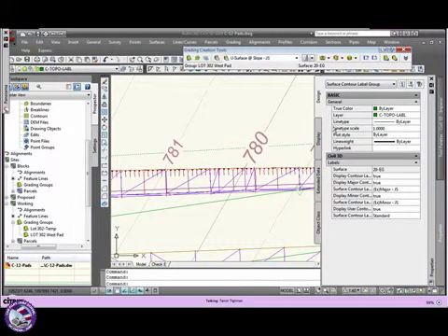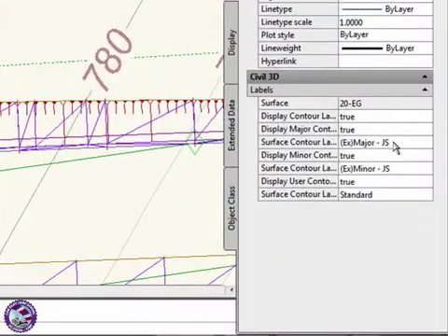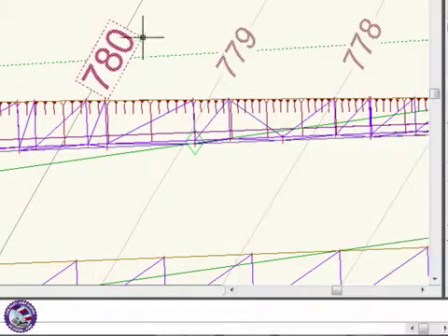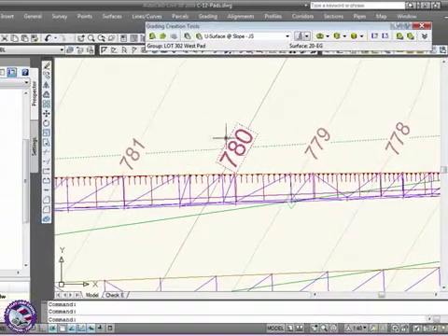And I need to move some stuff out of my way here. And here's the style. So we have an EX major style that we're actually employing there. We can change these, by the way, and let's do a box major. So you get little boxes, circles, and we supply all that kind of stuff. But your question is about a value inside a style inside Civil 3D.